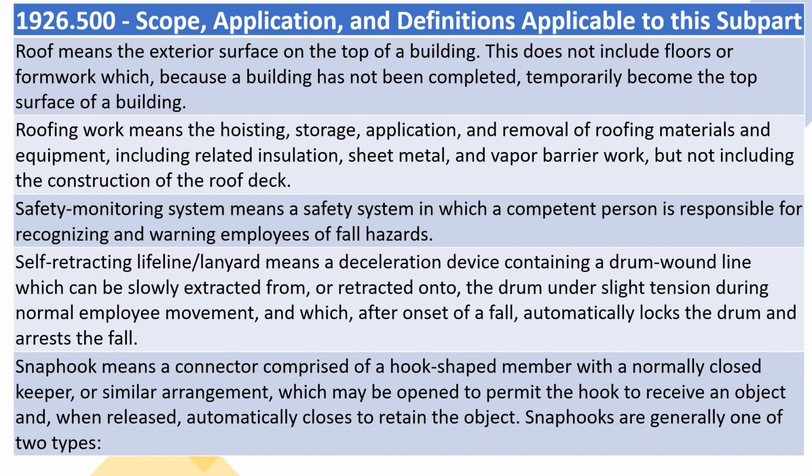Safety monitoring system means a safety system in which a competent person is responsible for recognizing and warning employees of fall hazards. Self-retracting lifeline/lanyard means a deceleration device containing a drum wound line which can be slowly extracted from, or retracted onto, the drum under slight tension during normal employee movement, and which, after onset of a fall, automatically locks the drum and arrests the fall.